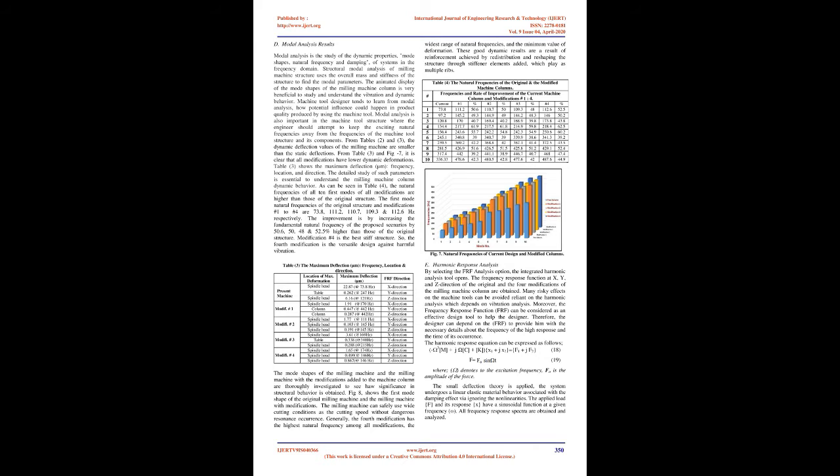The displacements X can be evaluated under the following assumptions: small deflection theory is used, linear elastic material behavior is assumed, there are no varying forces and inertial effects, mass and damping, while considering linear elastic material behavior, and some nonlinear boundary conditions may be included. The total deformation, U total in AM, can be calculated as follows (13), where U are the deformation components in the orthogonal directions X, Y, and Z.